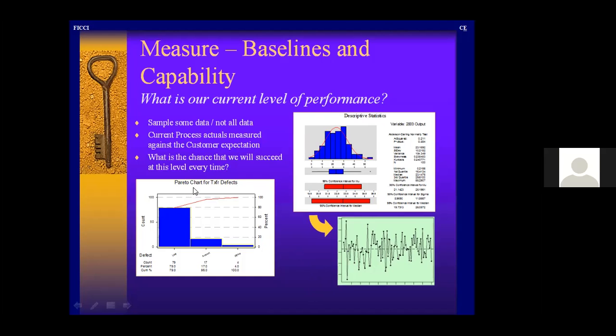So this shows the Pareto chart, Pareto diagrams. They are very common. Every mechanical engineer would know what a Pareto diagram is. So, for example, this Pareto diagram shows that the first are the defects which are majorly affecting, almost around 80% responsibility lies with these defects. The second category is not so important, and the last is the trivial defects. So we measure various types of defects, or the reasons, in the second phase.